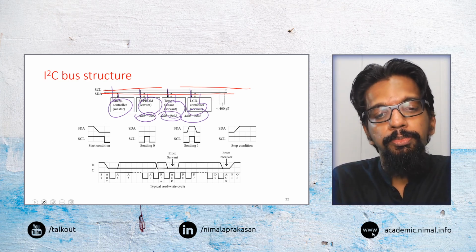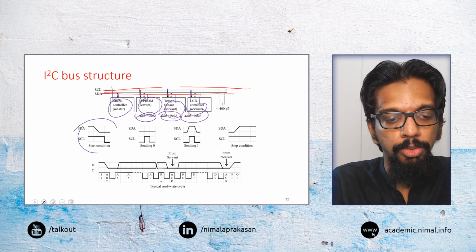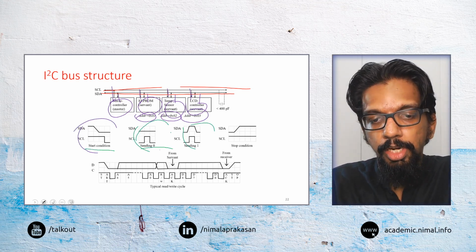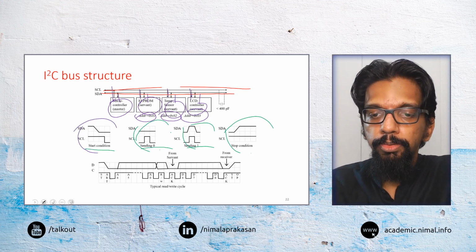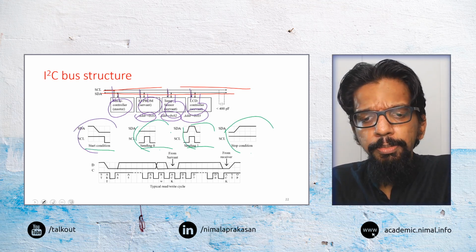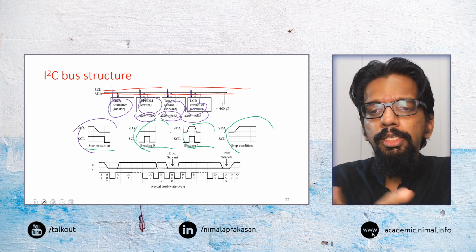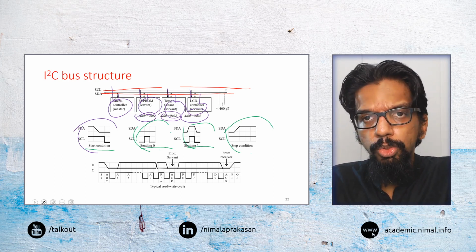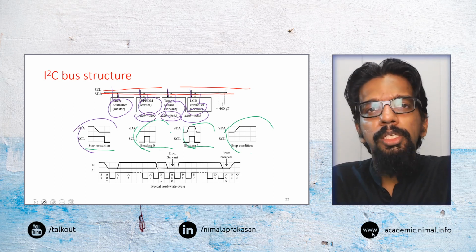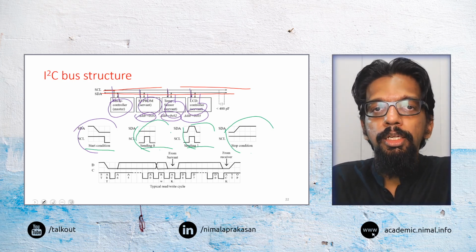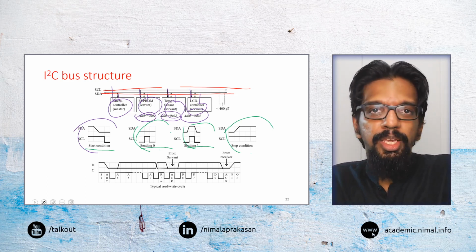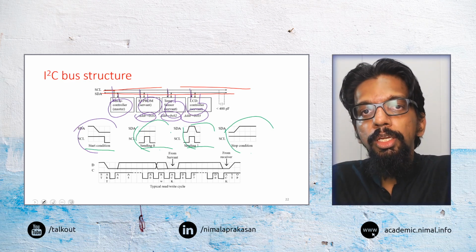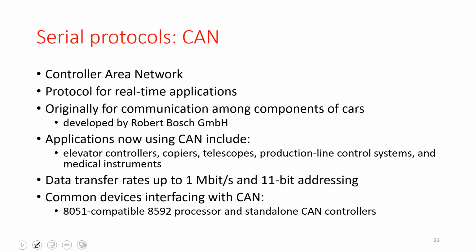This timing diagram shows how the communication happens in terms of starting, sending and stopping. So that is basically I2C. It is a basic simple serial communication protocol only using 2 wires, and even though it doesn't have much higher data throughput, it is still usable in basic embedded applications or applications that do not need higher data throughput.